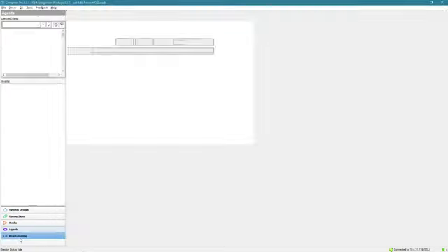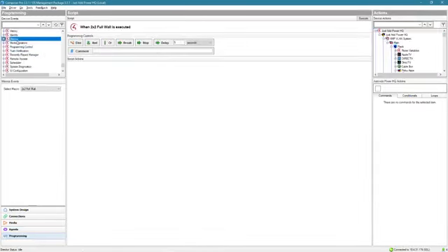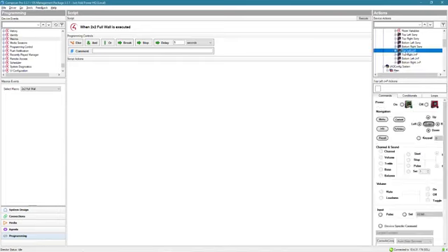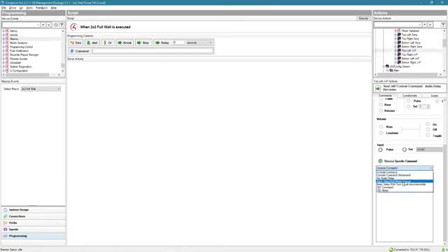We're going to now go down to programming, and this is where the magic happens. We're going to go down to our macros. We're going to start with our 2x2 full wall macro. So what this has to do is it has to build the 4 TVs into a single wall. And the way we have to do that is we actually have to do that with 4 individual commands, 1 to each receiver behind the television. So we're going to start with the top left, Just Add Power TV. We're going to go down here to device specific commands. We're going to go to basic video wall mode change.